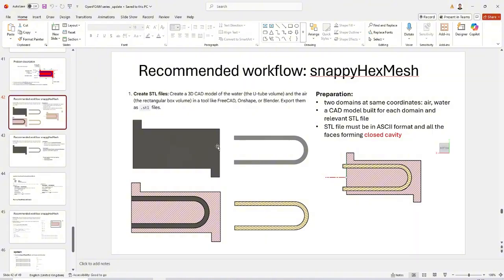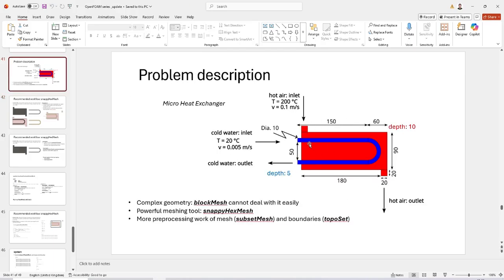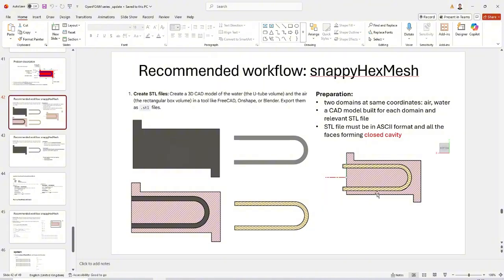So this is a cross section of the top parts, and make sure you build them in the same coordinate system, which means when you place them together, they should form the exact arrangement of your heat exchanger. Right here, as indicated, I have the X, Y. So this is my origin. I have the positive direction along X, and the positive Y and Z direction. If you use the right-hand rule, it will point inward.